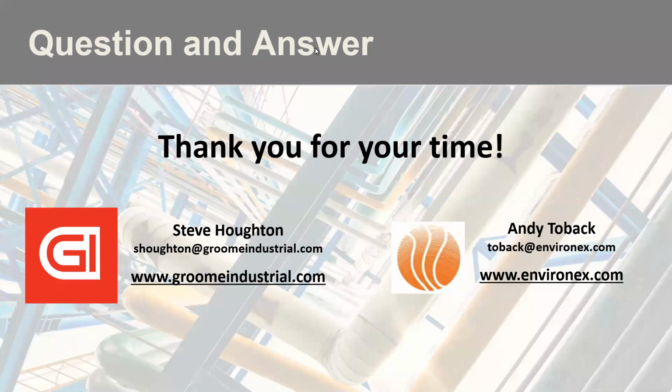Here's a question on the AIG tuning process without a sampling grid. How do you safely perform a traverse of an online HRSG? Wouldn't the gas be under a positive pressure? It is. And typically the stack testing unit that you bring in is prepared for this because they're doing the same thing at the stack. So when you're performing a RATA or a compliance test, it's the same procedure. They have safety measures in place to block the flow around the probe so that none of the positive pressure hot gas is escaping, or they're protecting their bodies from it.